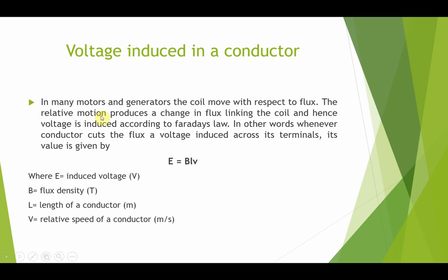The relative motion produces a change in flux linking the coil, and hence voltage is induced according to Faraday's law. In other words, when a conductor cuts the flux, a voltage is induced across its terminals, and its value is given by E equals BLV.